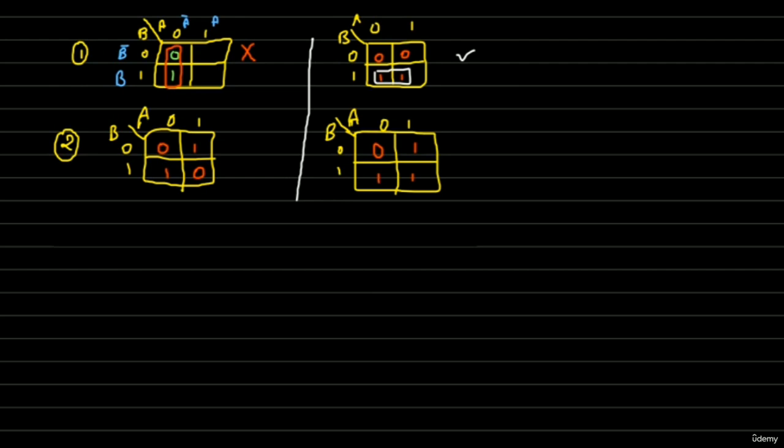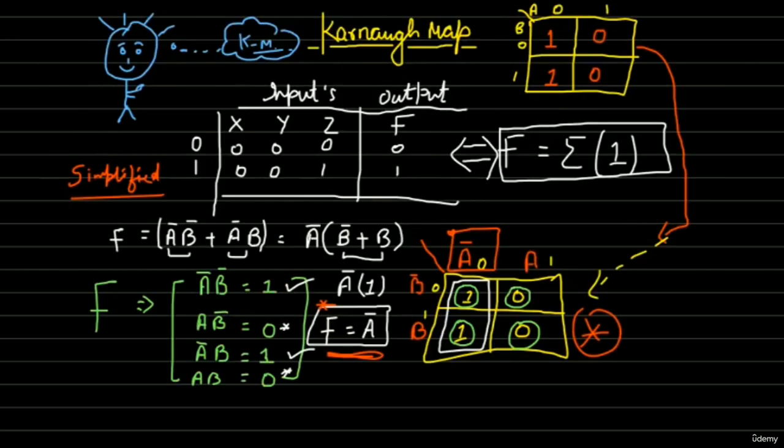So as you have already guessed, this is the wrong concept and this is the right concept. So why is it wrong? In the Karnaugh map system, diagonal pairings are not allowed. And why are we pairing all these things? If you are asking this question, I've started liking you. Well, we are trying to make the biggest pair possible of ones so that we can further simplify it, as we have done here. Let's just have a look here as we have done here.